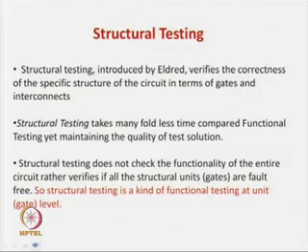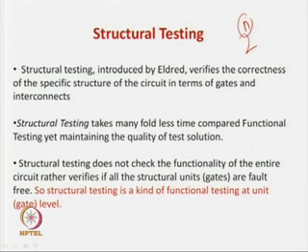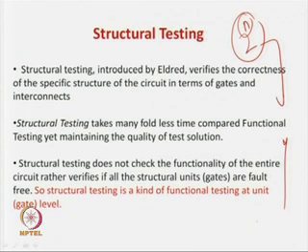Now, what is the solution? The solution is that we have to bring down this number, that is order of 2 to the power n, where n is the number of inputs. This order is required to do our functional testing. This we can bring down, the number of test patterns, or we can move up the test speed.